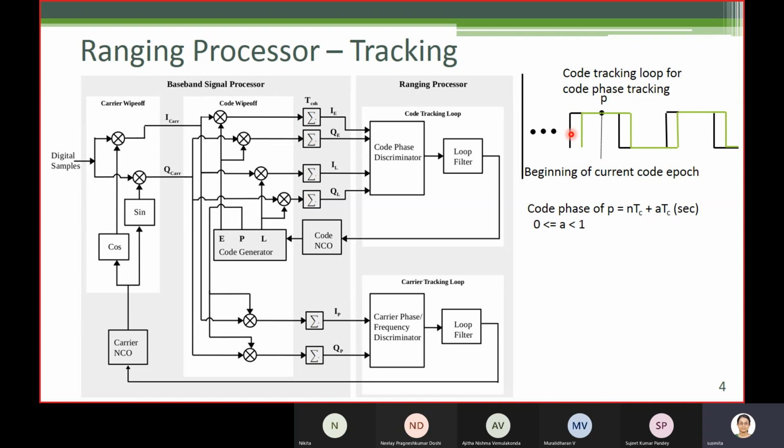What is the order of tau after acquisition? Since we have considered a step size for different candidate values of CP within a chip, say 0.5 chips, tau is within a chip, actually within 0.5 chip after acquisition. This error is of the order of less than 0.5 chips after acquisition.